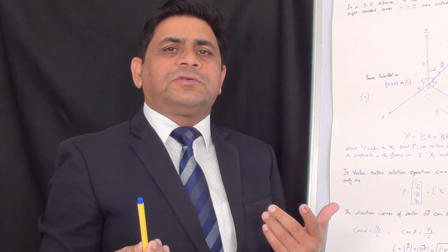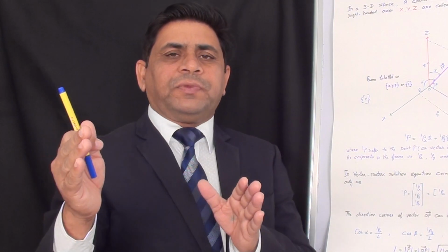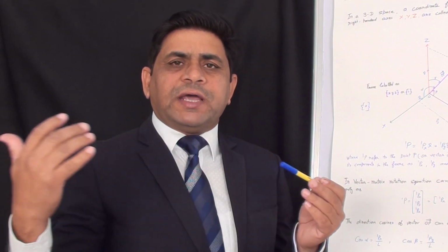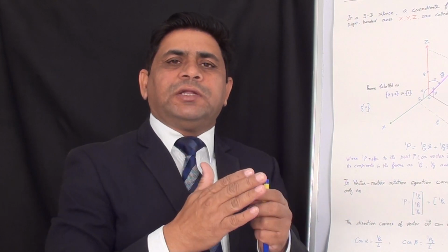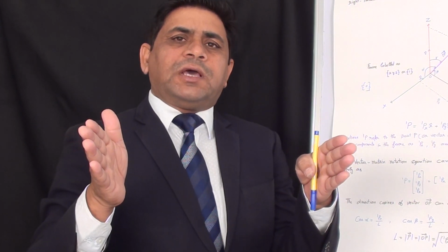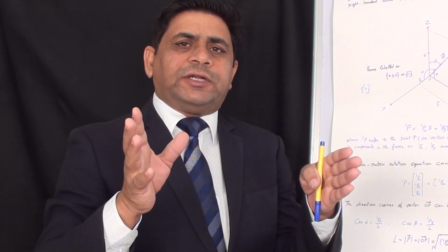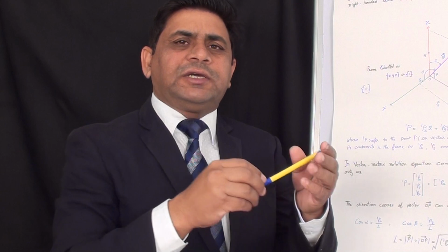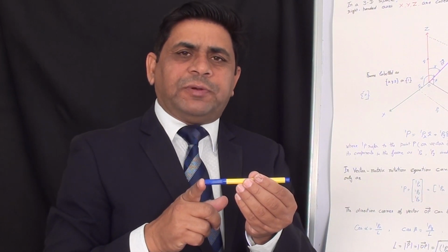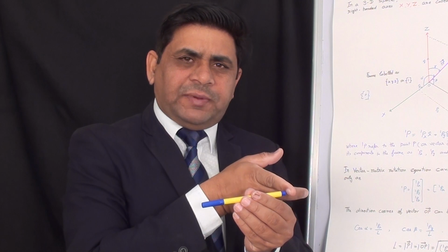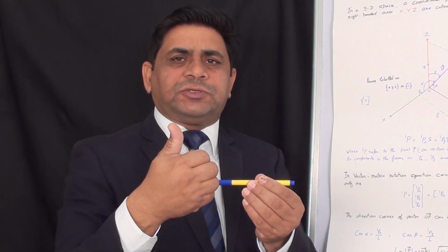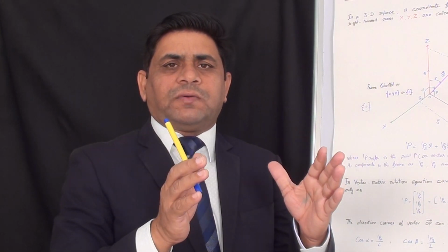In my next lecture, we will find out the relationship between one frame and another frame. While finding out the kinematic analysis, some of the joints are revolute joints, some are prismatic joints. In the case of a prismatic joint, there may be a linear transformation. That means if one frame is linearly transferring to another frame, there may be mechanical constraints in which one of the link parts is translating as well as rotating. If we are assigning one frame at the end of the manipulator link and one frame on the base of the manipulator link, and it is rotating and translating, then the mathematical relationship needs to be found out.